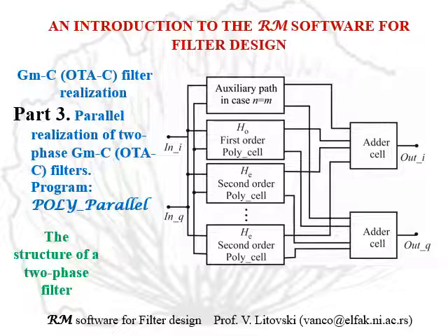The idea is to have two signals, I and Q, and they are processed in parallel, which means there are two identical filters processing the I and Q signal, which, in fact, are mutually coupled to allow for the shifting of the passband on the omega axis.